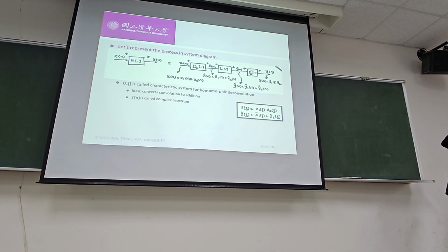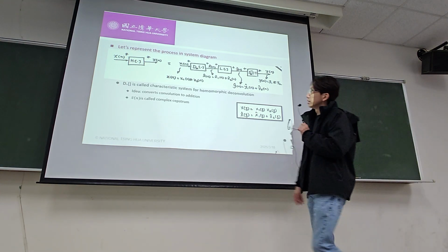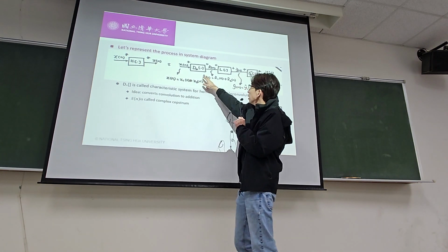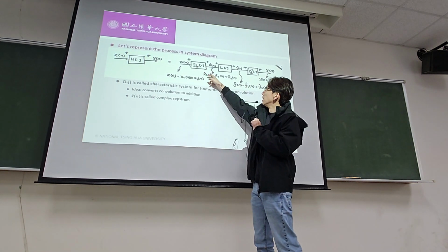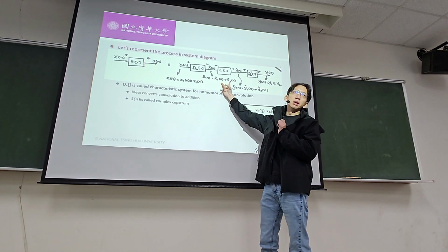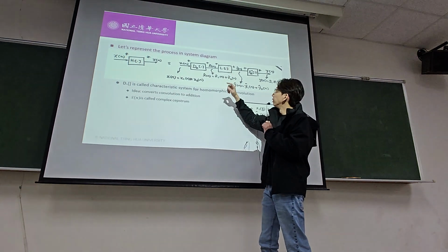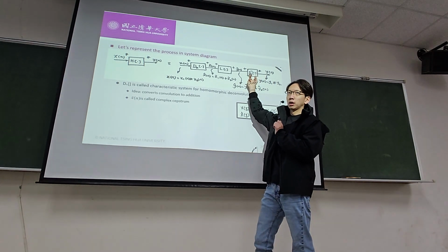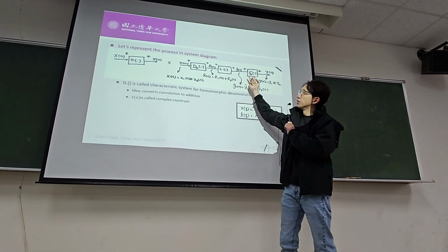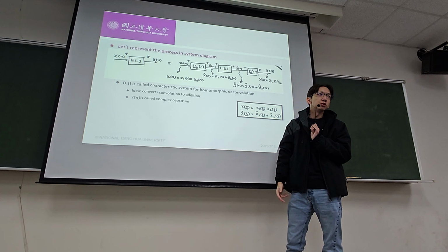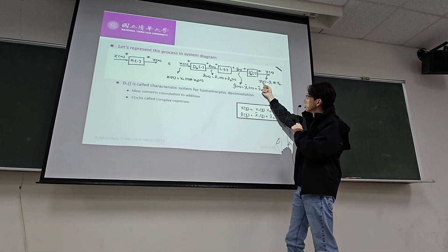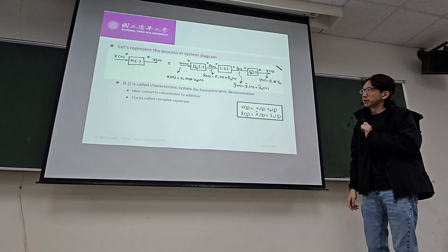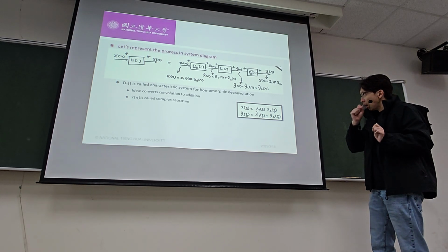So we can represent that entire process. If your x[n] is originally something convolved through some functions, it goes into a new domain that makes them additive. Now you design a linear filter that processes them individually, then come back through the inverse of that characteristic function, or transform, and you get back to the original as though they were convolved. This D we call the characteristic system for homomorphic deconvolution.